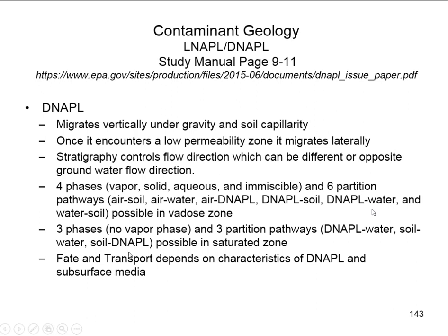So the stratigraphy becomes very important for the DNAPLs to get the orientation of any of those clay lenses or things that could divert the migration of the DNAPL away from where you might have expected it to go, but it didn't go there.